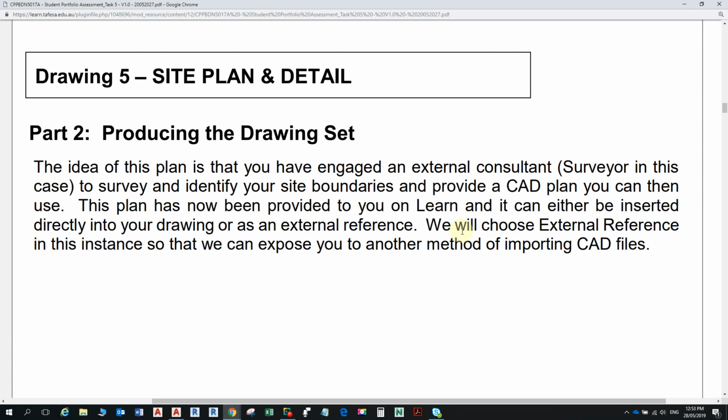The advantage is that it keeps the file size smaller for a start. But the bigger advantage is this: if the architect ever changes that floor plan, you just send a new one to all those people. Next time they open their drawing, they see the new walls appear or whatever, and you send them an email saying, look, I changed bedroom 3 to this, and they look out for that and make their changes accordingly.